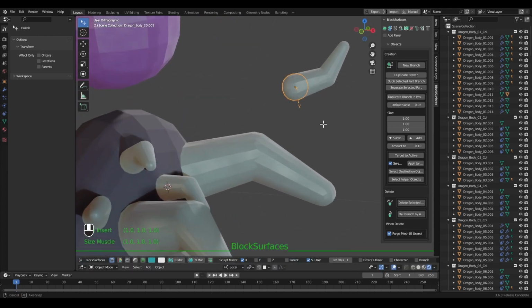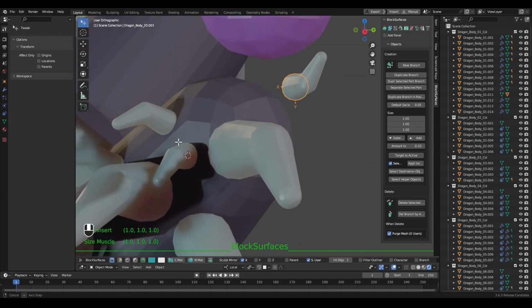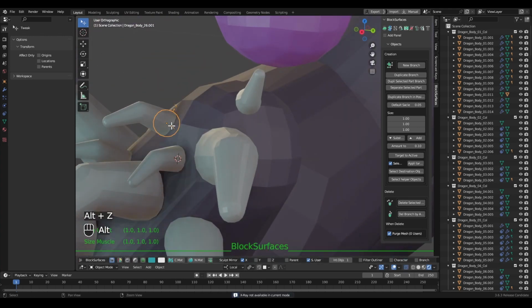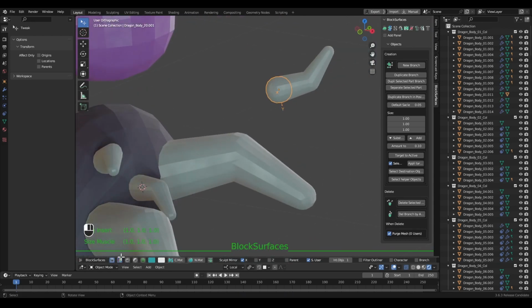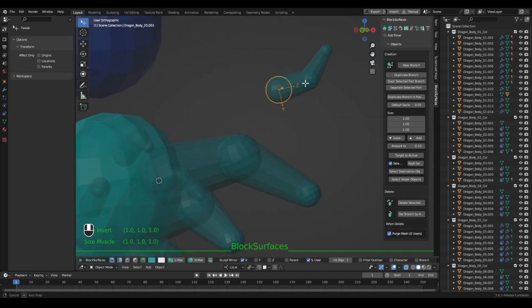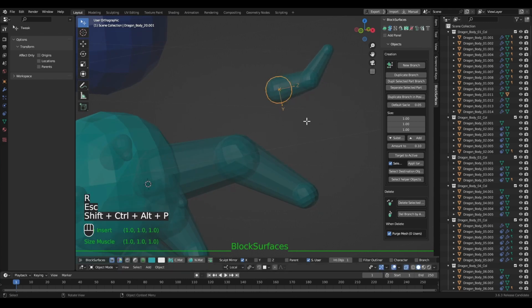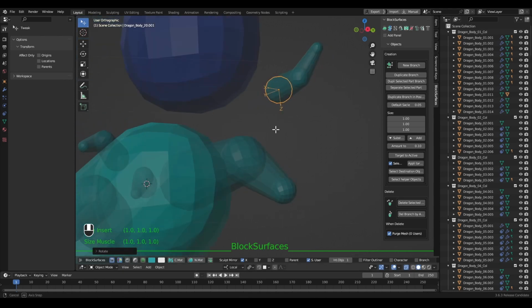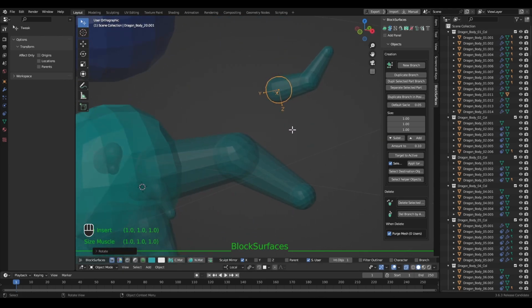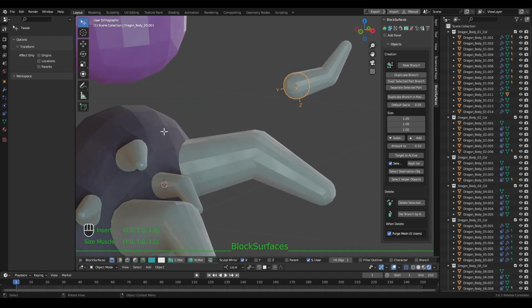The orientation with which the new branch will be inserted on the surface will be with the Z-axis facing upwards. So when we want to have a surface with a branch oriented towards the surface, we must adjust the Z-axis so that it stays facing up, and when pressing the K shortcut key, it will be the Z-axis that aligns to the surface.